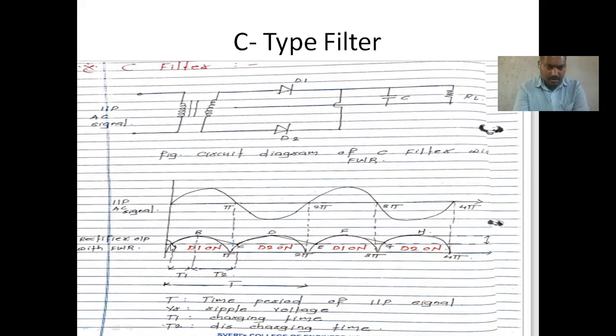See, the voltage comes up to this level, increases again, and goes to this level again. So the voltage across your capacitor has less AC component. That's why a C-type filter reduces the AC component, but it is not fully reduced, because a capacitor alone does not fully reduce the ripple. It requires more components, that is CLC, the configuration which reduces more ripple in the circuit.